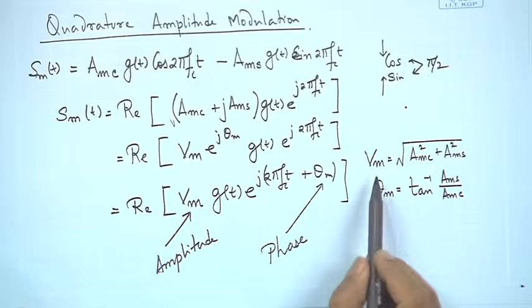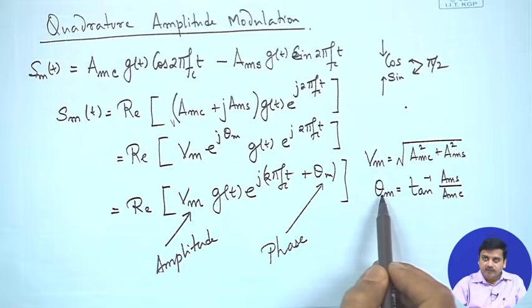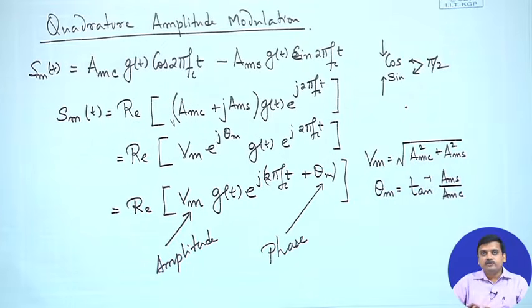That did result in different amplitudes in the I and the Q components, but they were constrained by the phase. Whereas here you have two things to select, amplitude and phase, or two different amplitudes. So these are the two different views of quadrature amplitude modulation that are usually available. We'll take one of the views first and then look at the other view after a while.